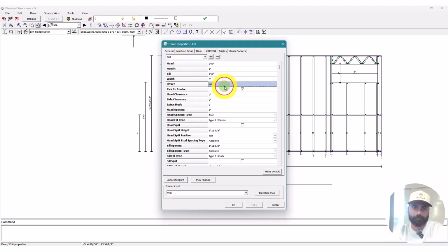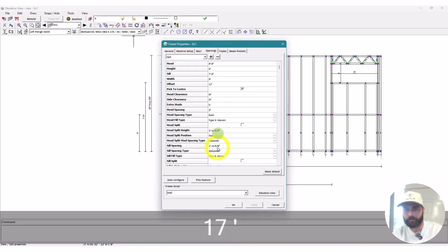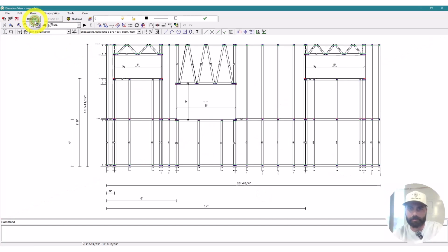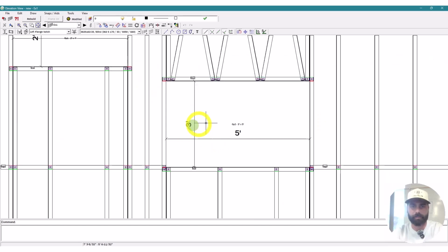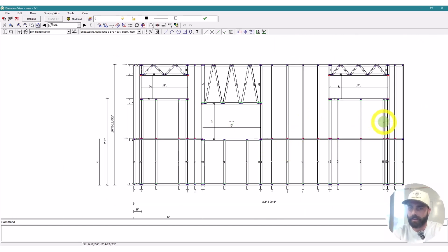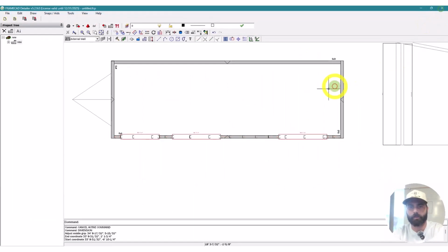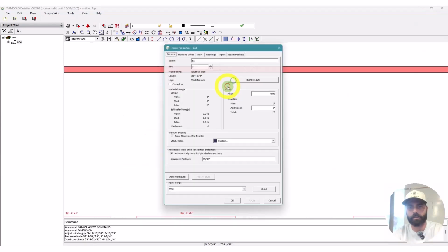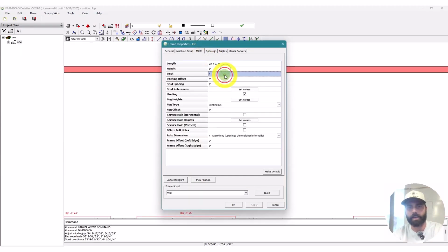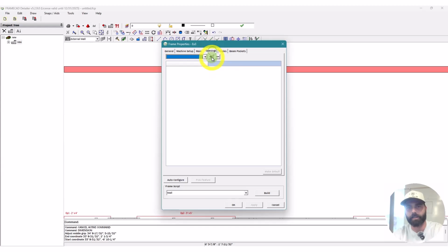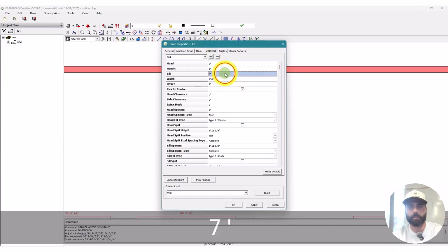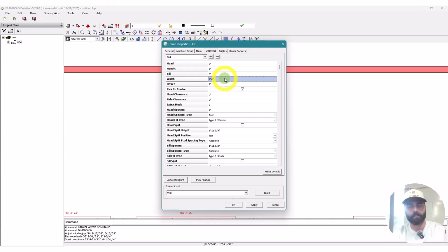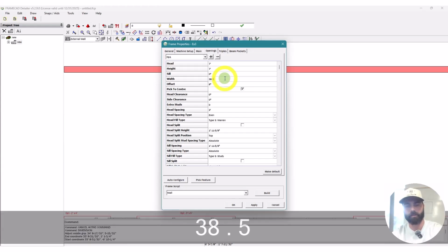Okay. So we've got our little tiny house here. This one's 5, this one's 4. Here's a window there. We'll jump to the other wall real quick. And then this one will make that 9 foot. We'll go ahead and add the door. So it'll be a 7-foot door. That's a 0-inch sill height. We'll make it 38.5 inches. And then we'll offset the door 16 feet.